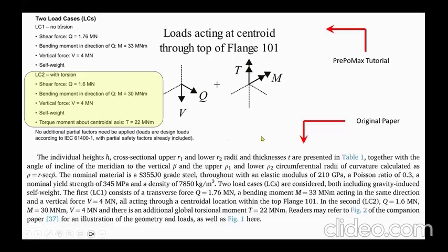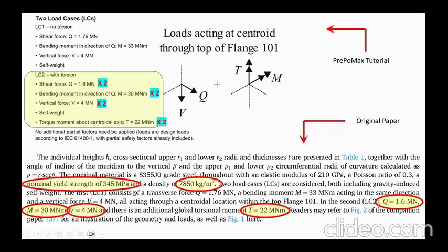This is the details of what's given here, as I mentioned. Because we're doing fully plastic or elastic plastic analysis, I need to know the yield strength. It's right there. And this is all the loading information above. We need the density because we need the self-weight. And in fact, these are the things that I already used in tutorials 11 and 12 of the buckling analysis of the wind tower.